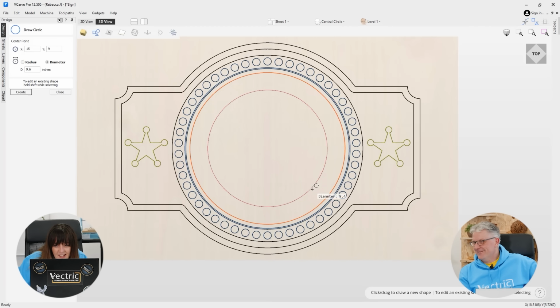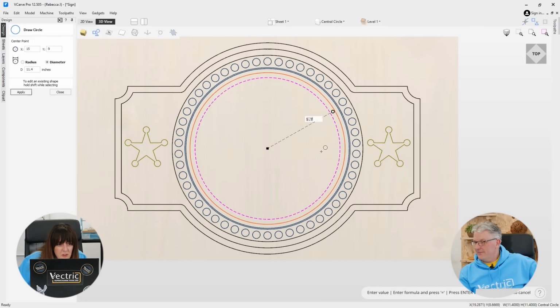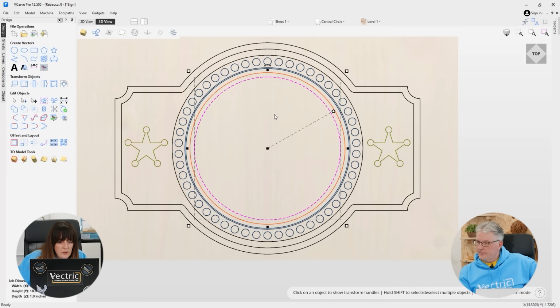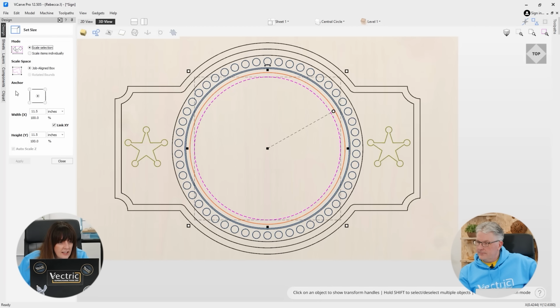So we're going to pause that again. I'm just looking at that field as Todd mentioned earlier and just going to skirt around the 11.4. I actually want to change that so that the diameter is 11.5, okay? Kind of want decent numbers here. And then we could do that trick that Todd said earlier, T, and I can see it's definitely 11.5. I've remembered that already.